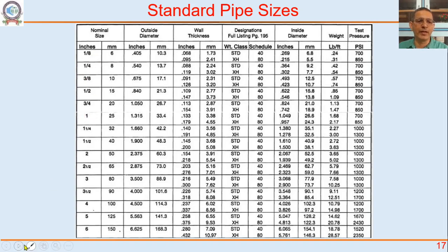So for example, if we take a 1 inch pipe, you would expect the diameter, 1 inch is 25 millimeters, to be 25 millimeters. It's not exactly 25 millimeters. It depends on the thickness of the pipe. You see, if it's a 1 inch pipe, the outside diameter is not 1 inch, it is much larger than that. Thickness is written in terms of something called a schedule.